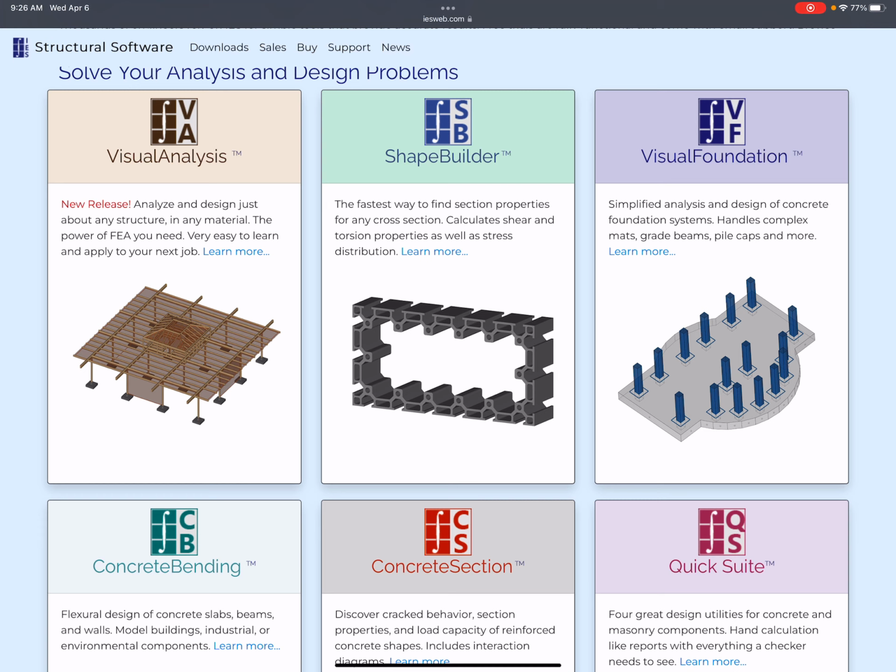Shape Builder, that's also a big benefit. AE Dynamics, a structural engineering firm in town, does a lot of curtain wall design, so extruded aluminum stuff. If you look at the front of Norm, the big windows in Inspiration Hall, they're actually structural. The mullions, the horizontal and vertical members in those windows, actually carry the glass and the wind pressure on the glass.